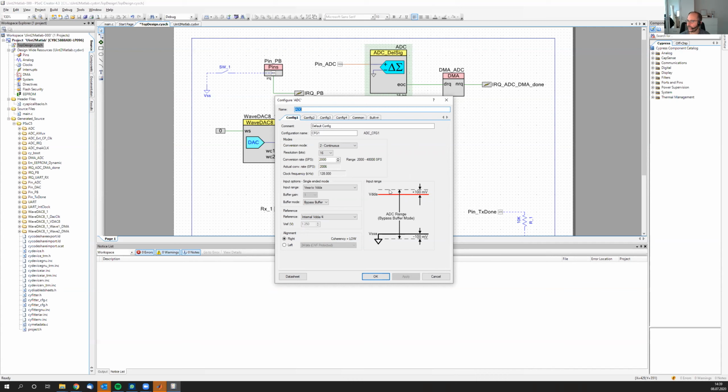But the general idea where I want to go with that is basically we have an ADC range, then our value range going from 0 to 65,536, so 2 to the power of 16. This basically reflects the entire ADC range. And so if we get a value out of that, this will give us a relative position in this range, basically, okay? Now, for the assignment, it was asked to provide the graph as voltage, okay?